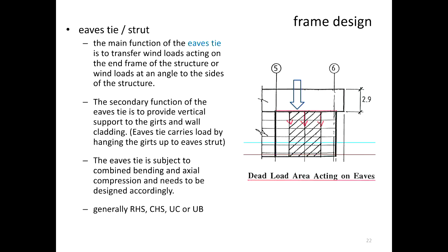and then it's usually used to provide support for the girts, because the girt goes this way, so it provides vertical support. It acts as an anchor where the girts just hang on, moving down. So it's been sort of tied. Usually the bridging will be tied to the eaves tie in most cases. As I said, it's very hard to explain, especially this particular slide. But when we go to site, hopefully we might be able to see that.